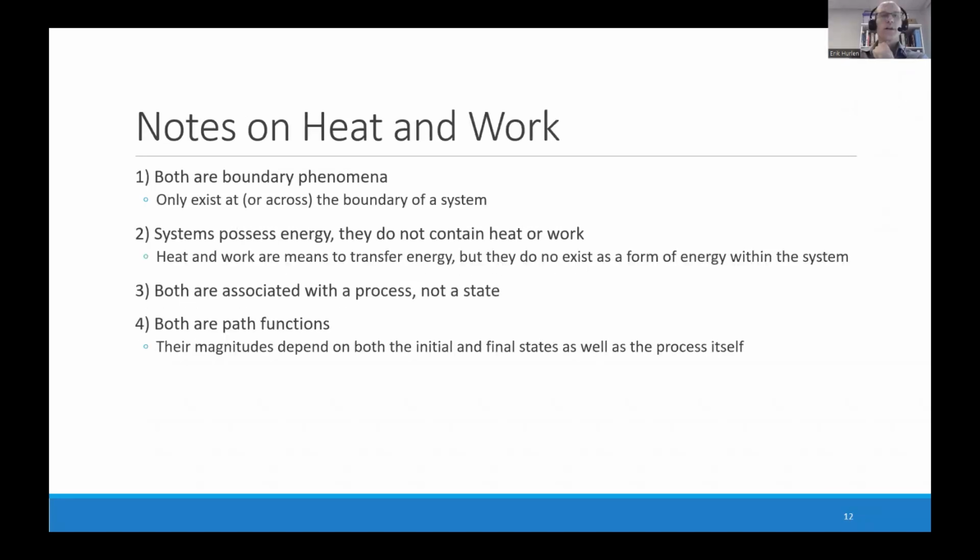A few things to keep in mind when dealing with heat and work. They both only act at the boundary of a system, not inside it. Because of this, the system does not contain heat or work like it does with other forms of energy. Similarly, these other forms of energy help to define the state of the system. Heat and work are associated with processes, not with the state of the system. They help to define how the system is changing. Both heat and work depend not only on the initial and final states of the system, but also how it goes between the two.